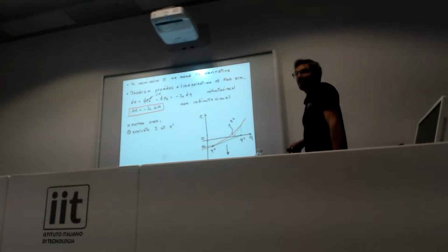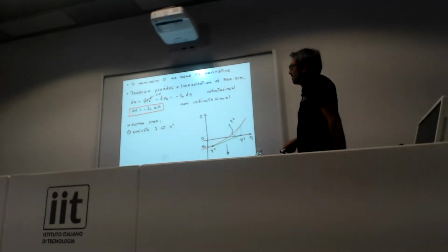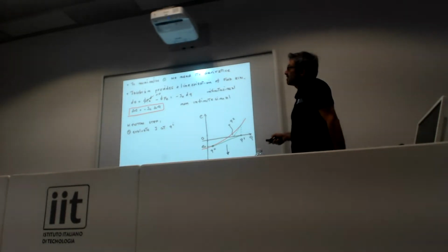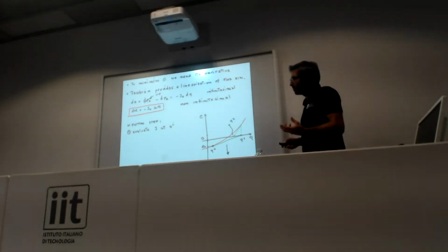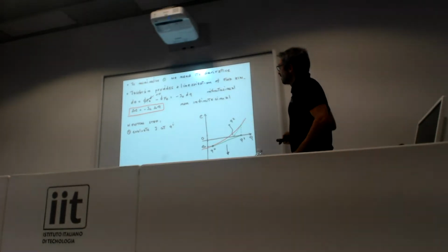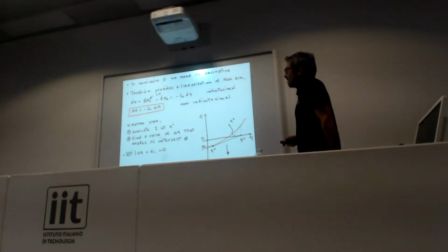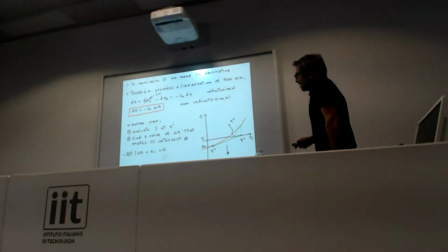Then we can apply all this in a Newton step. This means first we evaluate the Jacobian at the initial configuration, and define in essence the linear approximation of the forward kinematics.